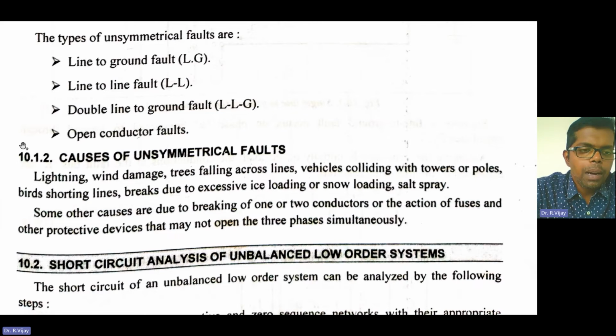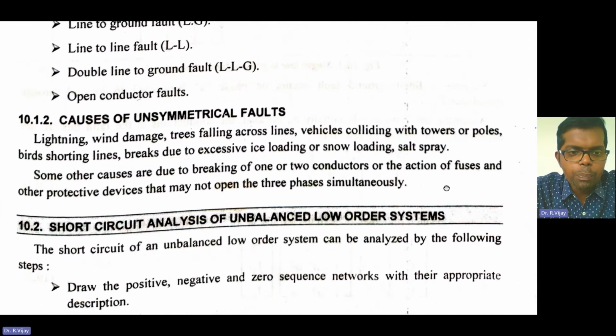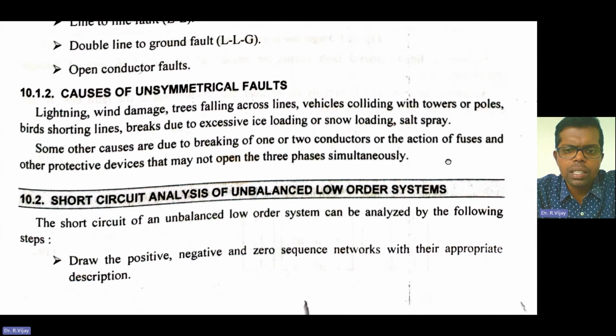Some other causes are breaking of one or two conductors, or action of fuses and other protective devices that may not open the three phases simultaneously. Breaking of one conductor or two conductors, or action of a fuse, and other protective devices that may not open three phases simultaneously. So this three phase fault is rare. Sometimes it might happen also.